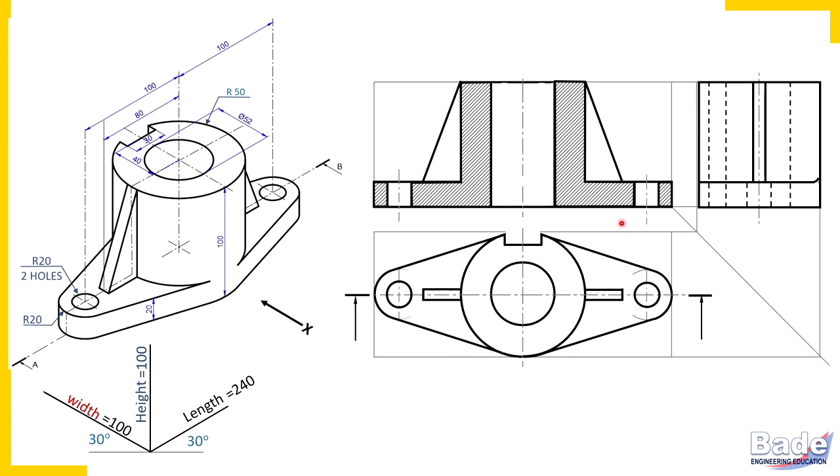On your screen, watch this sectional view, know where there is a hidden line. If the largest surface of a plate appears in sectional view, then don't show hatching lines on the largest surface of the plate. Such plates are to be assumed uncut.